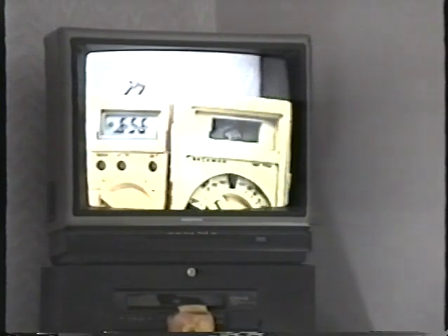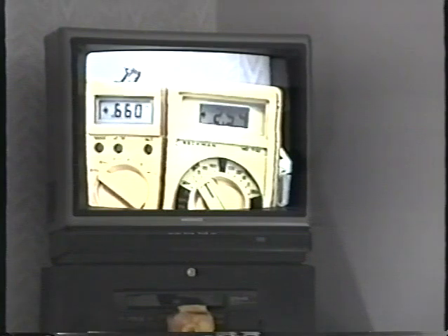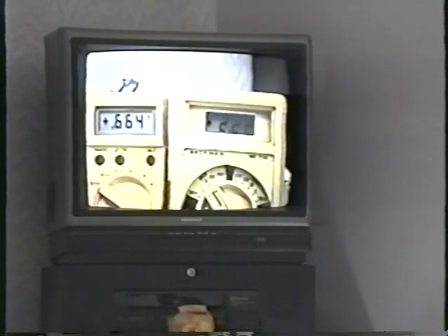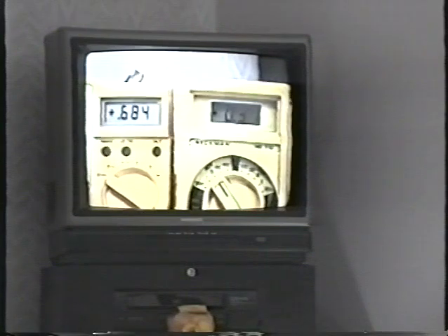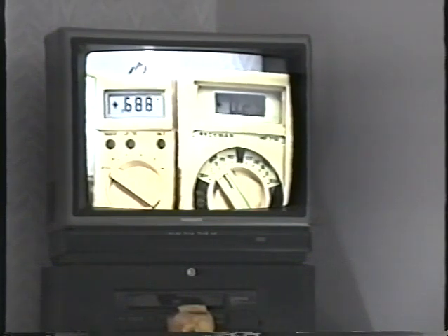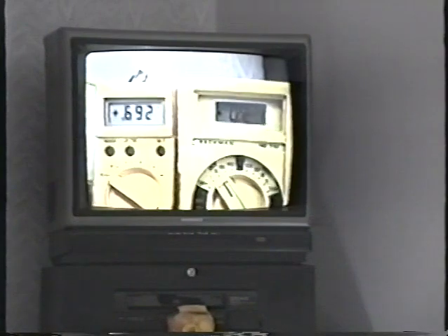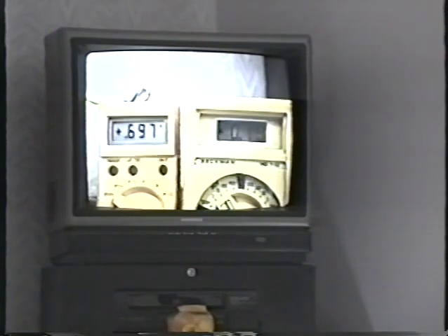Let's see if I can turn this back on now. I flipped over that one. There we go. So here we go again. And watch what happens now. As I increase that base voltage just a little bit, that collector voltage drops like a rock. I mean, the base voltage is only moving up by thousandths at a time, and look at the collector voltage drop like a rock until it can never go all the way down to 0. There's always a tiny amount of voltage left. In this case, about 1/10 of a volt, well, 0.16. The collector can never completely short to the emitter.